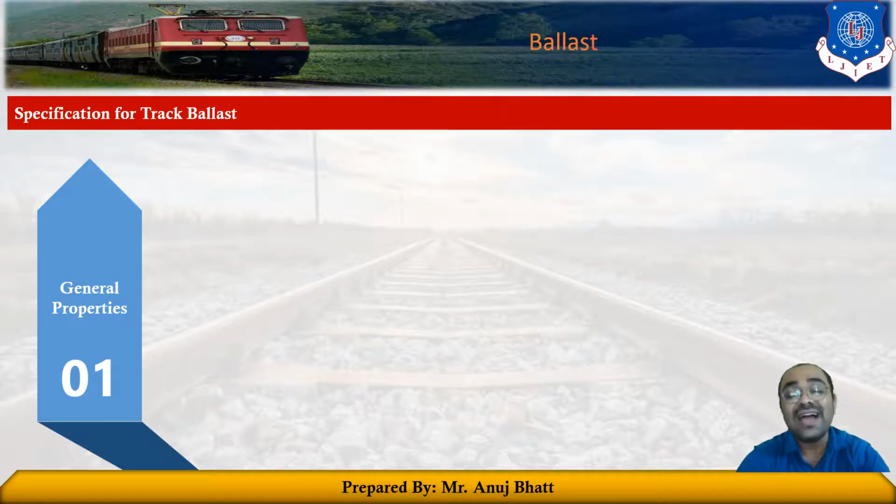Before using hand broken ballast on broad gauge tracks, prior approval of the chief track engineer is nowadays required, so that they can check whether the stones used for the ballast are machine crushed or not, whether they are too flaky or too elongated, and whether they have a sharp edge or not. These checks are very much required before applying that material for construction.